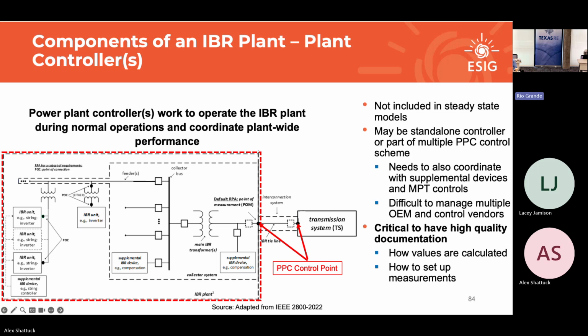Just to add one more complexity to that. When you have multiple PPCs, a lot of times you put a master power plant controller on top of it. Now, who handles the voltage control? Who handles the primary frequency response? The Q commands get sent. Are they voltage commands? Where does the set point go? Very complex. Then each has their droop and dead band, and ramp up, ramp down. And this is just from experience.